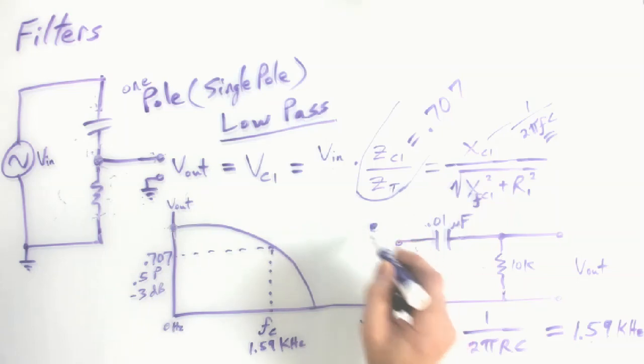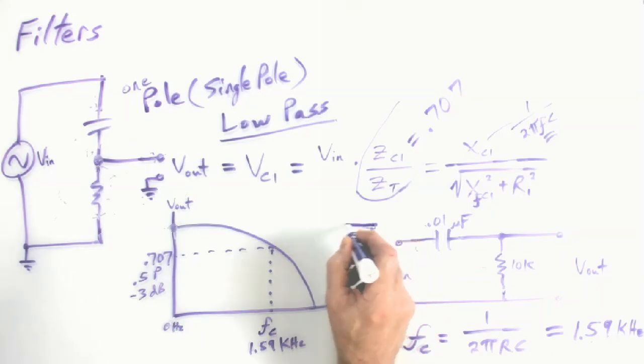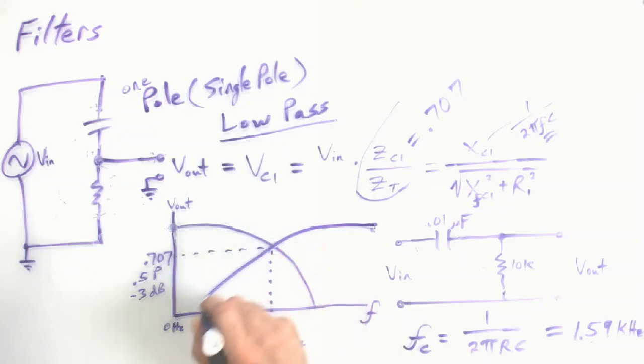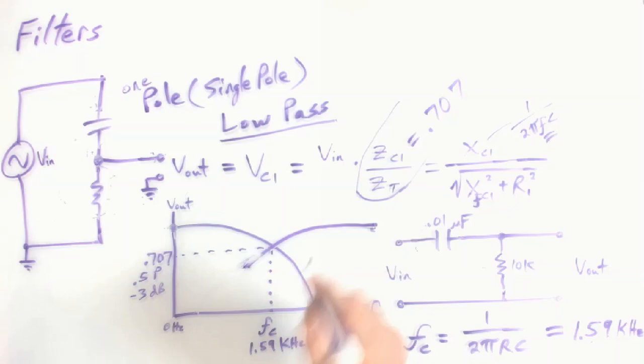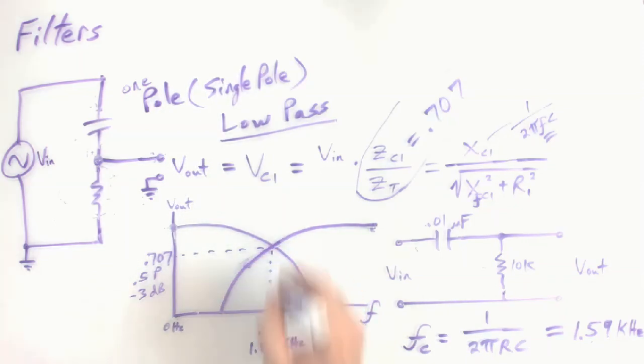So let's draw that as frequency decreases, the capacitor's impedance increases, and it claims more of the voltage as it sits in a voltage divider relationship with R1. So frequency is going down, capacitor's impedance is going up. Yeah, this kind of a thing. Didn't draw that real well. I meant to sort of have more of a roll off there. Okay.